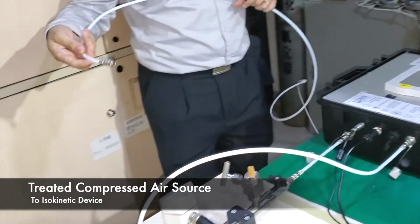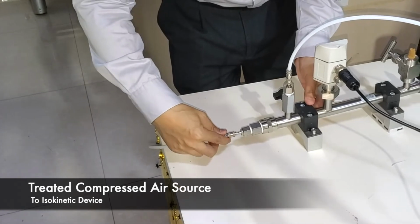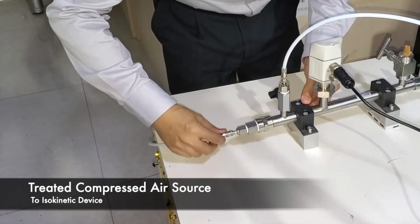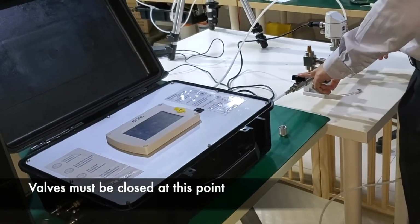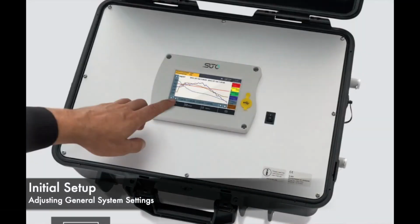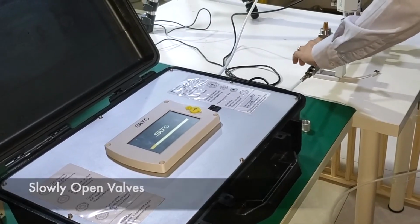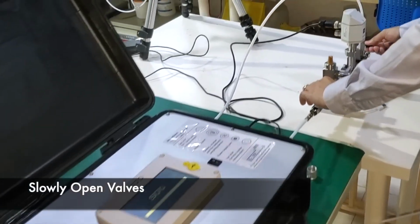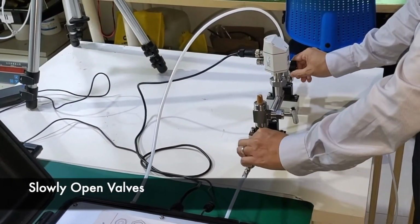At this point, we're ready to connect our treated compressed air supply. Please make sure that the ball valves and the needle valves are closed at this moment. Once the S600 unit is powered on, slowly open the compressed air valves. This will avoid any damages in the internal sensors.